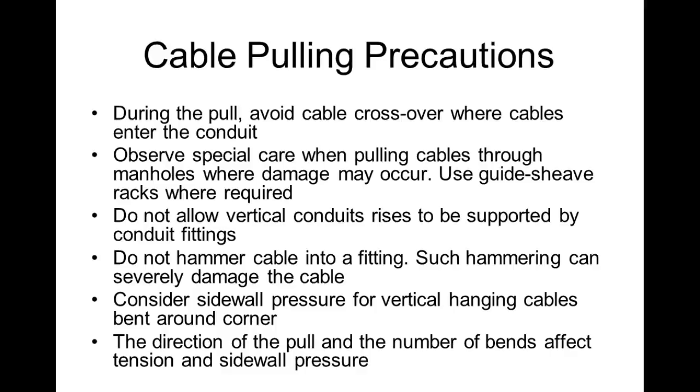This is especially true on EMT. On EMT, you never want a joint to support the conduit. Everybody understand that? You want to bolt that stuff to the wall, right? Do not hammer cables into fittings. Such hammering can damage the cables.